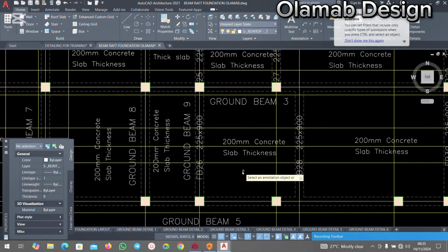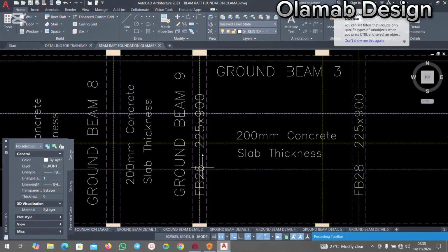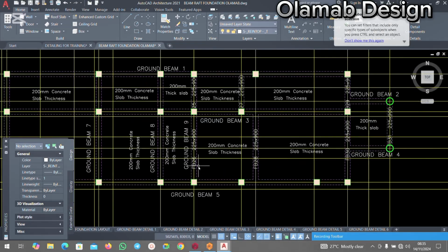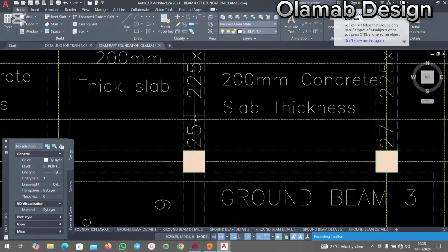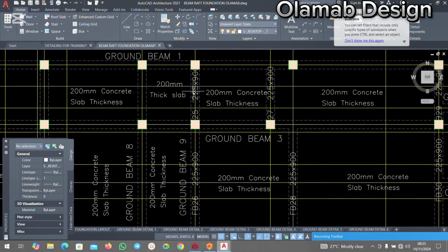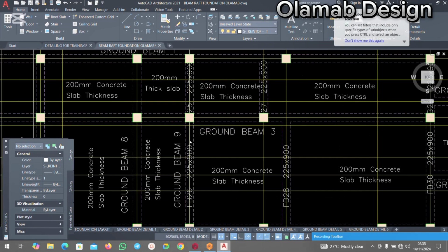You left click on it, as you can see. This is foundation beam 26, that is 25 and 26. You can see that already, since we have relabeled our members properly in Prota Structure, even the beams are aligned with each other. So you have to note all this. Before you export your design, you must make sure you export your design in a way that is going to be well arranged. Okay, this is 9.